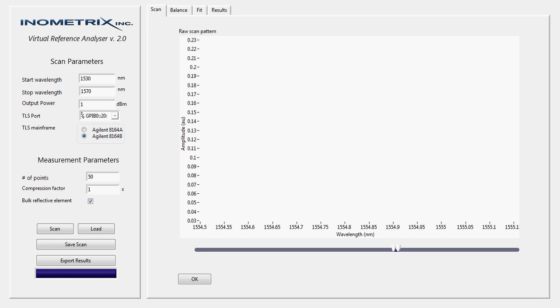Side A of the fiber Bragg grating, and this fiber Bragg grating has negative dispersion. It's a dispersion compensating grating. Okay. Now, the settings on the amplifier inside the VRA is set to 0 dB. So the gain on the sensor is at 0 dB, and this is actually crucial for measuring DWDM devices.